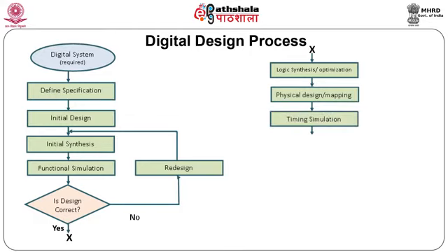Once placement and routing in the physical design is complete, then the final stage of design is carried out through timing simulation. In timing simulation, the propagation delay of the logic circuit is evaluated and verified with expected design parameters. If the timing characteristics of the digital systems do not match, then designers must redesign at physical level.